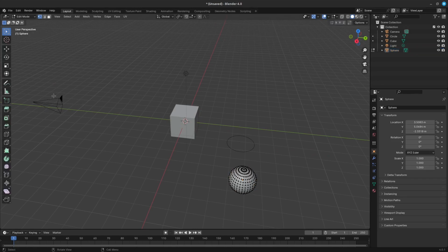After this, you can drag the region outwards. You can also do this more quickly with the shortcut, E on your keyboard. Let's go back to just having the box select tool and grab a few more vertices and then pull it out, and that's extrusion. You can use this to make any number of shapes that you want.